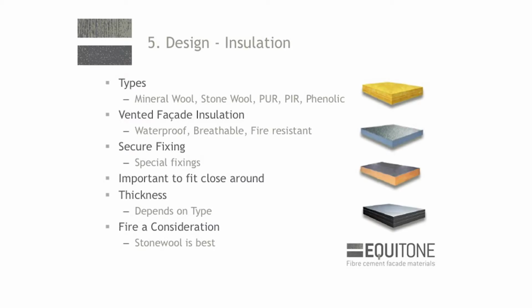Insulation for the cavity space. Mineral wool, stone wool, in simple terms Isover, rock wool, and then you have all of these PIR and phenolics. Which one would you more commonly use here, do you think? Glass wool, the Isover ones, yeah? And EPS. Right. EPS, that's the polystyrene stuff.